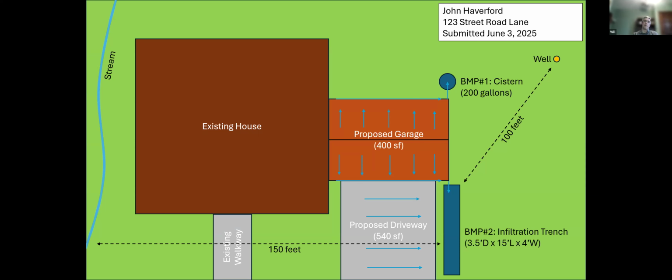So I would suggest building that into your submission to the township, so that if you're going to convert this walkway from impervious to pervious, that is reflected in the documents with the township, so you get credit for that reduced impervious area. Thank you, Will. You're very welcome.